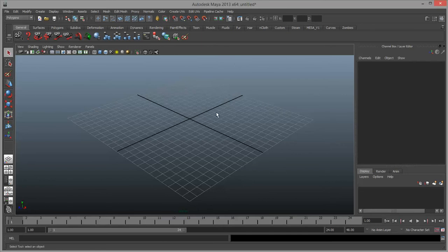Okay. Now, this main screen area is our view of the 3D world in Maya. This is the grid drawn onto that screen to get our orientation. You can see down here there's the word "persp", which stands for perspective, which is the view that we're in, which is not locked along any of these axes.